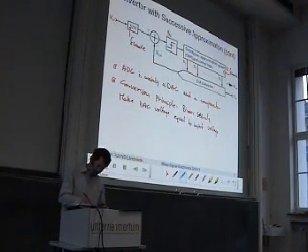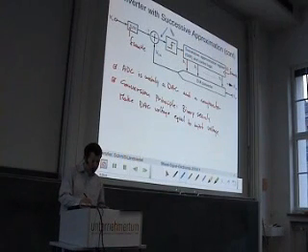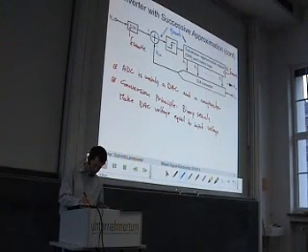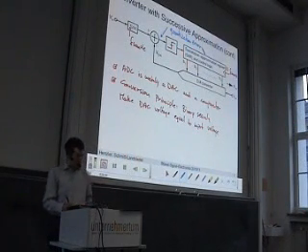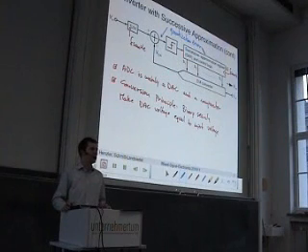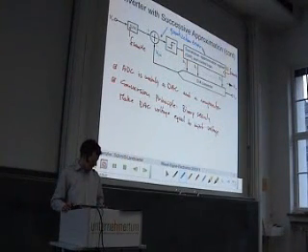Also interesting to note is that the difference between the internal voltage and the sampled input signal is exactly the quantization error. This is good to note if we go into architectural details today.